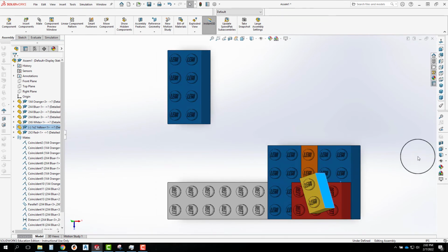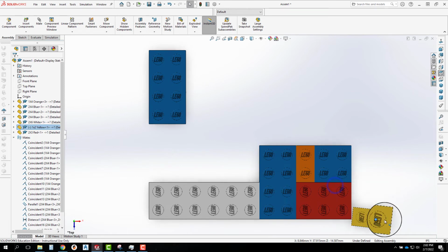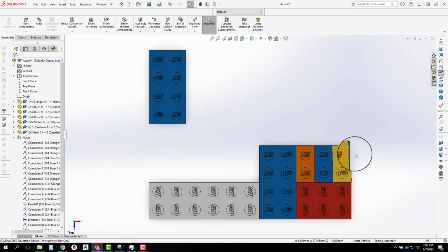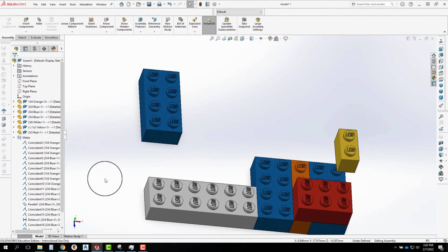This edge is always going to be coincident with this plane, that leaves a lot of degrees of freedom for the rest of the part, right? I can rotate about that edge basically. So that may be useful. You may have some type of orientation where you want things to be able to move. A hinge maybe could be a use, you'd want something where it can rotate about an axis. You could do that with concentric as well, like we talked about. That would actually probably be a better application there. But okay, let's take it back.